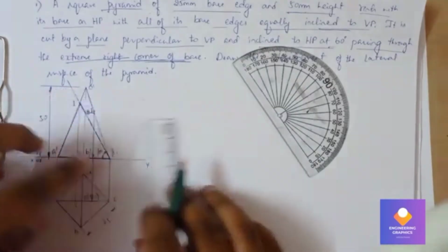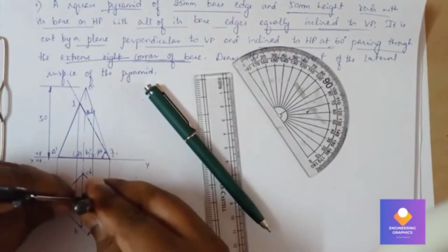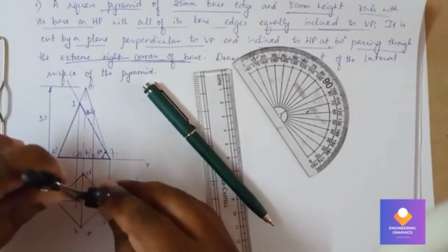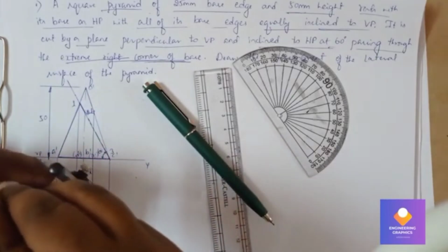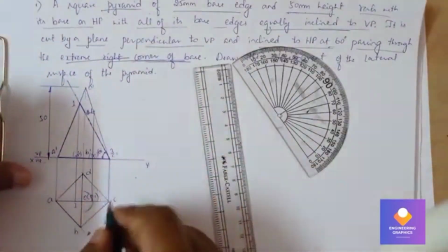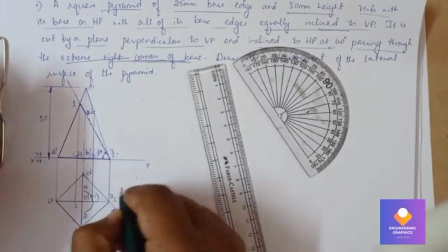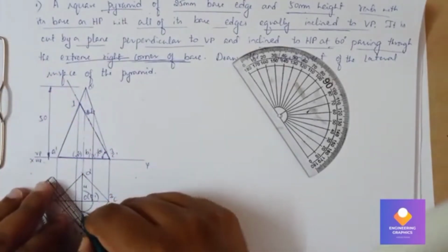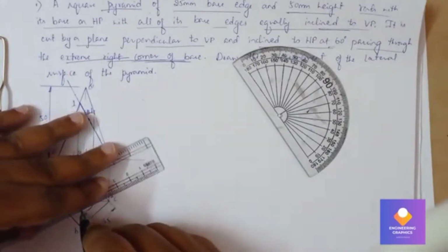We don't know exactly where it is cutting. So we can measure the length from that, then draw an arc or a semicircle to OD and OB. So you can cut the arc. So that is our points 2 and 4, and this is point 3. You can join these points 1, 2, 3, 4. That indicates the cut portion, how it is cut by the section plane.